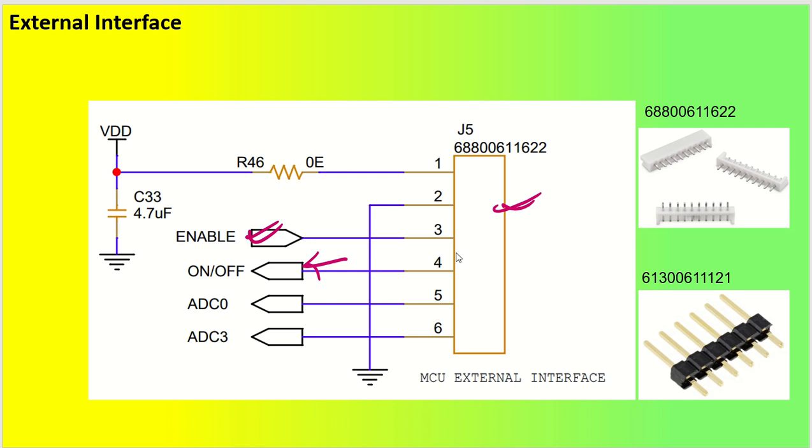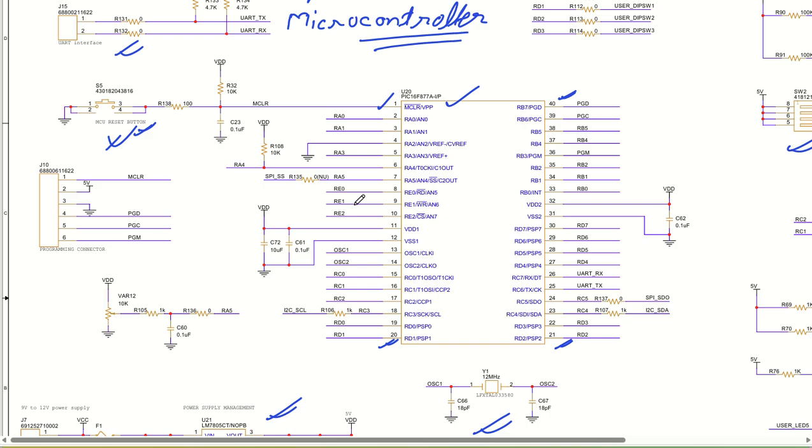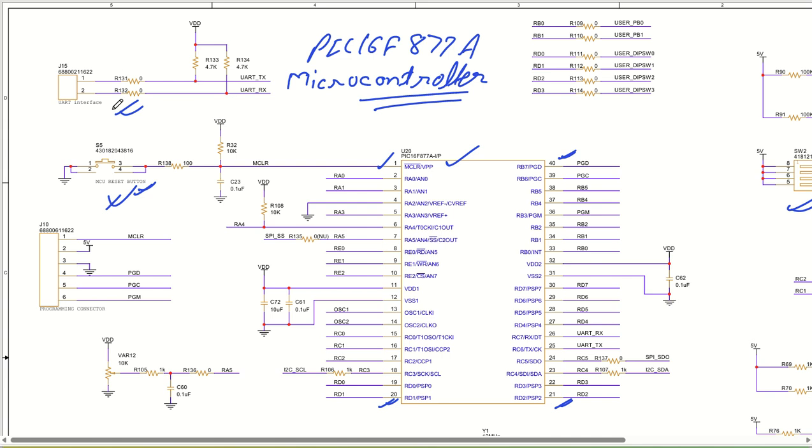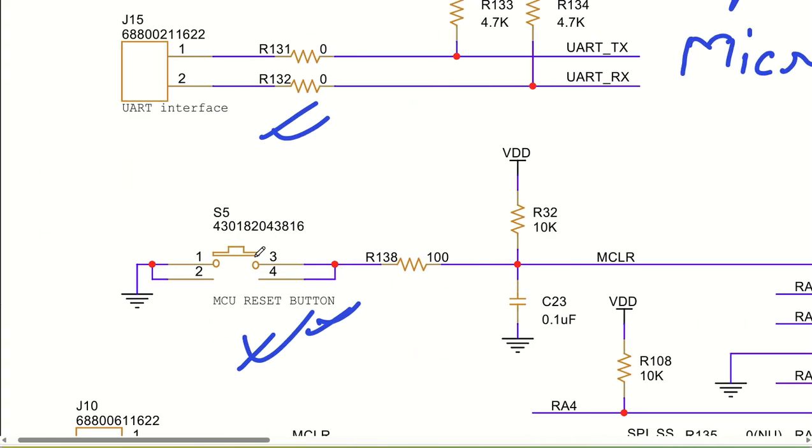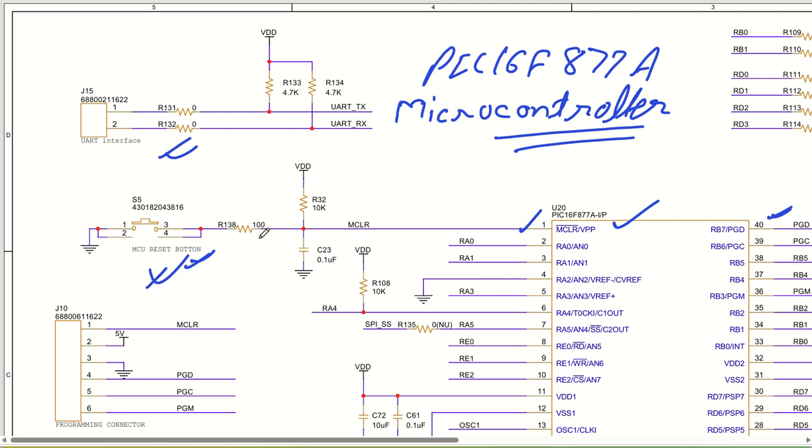Okay, so all these things one by one you saw. Now let me just open the circuit where you can see very easily the complete design. So as I told you, this is the reset switch. If you want, you can put the part numbers as well, so that you can have a complete understanding of how it is. And I have put a resistor in series also, so this can be utilized to make sure that it doesn't immediately reset. It takes a little time to switch off.